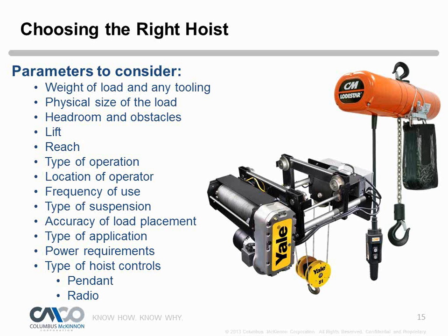The power requirements are very important. What voltage are you going to supply for it? Single phase, 3-phase, and the voltage requirements for that hoist. And then the type of hoist controls, which also goes along with where the operator is located. Do we need a pendant or a radio remote? We want to make sure we get all that information up front, and then we should be in fairly good shape to size the right hoist for the application.